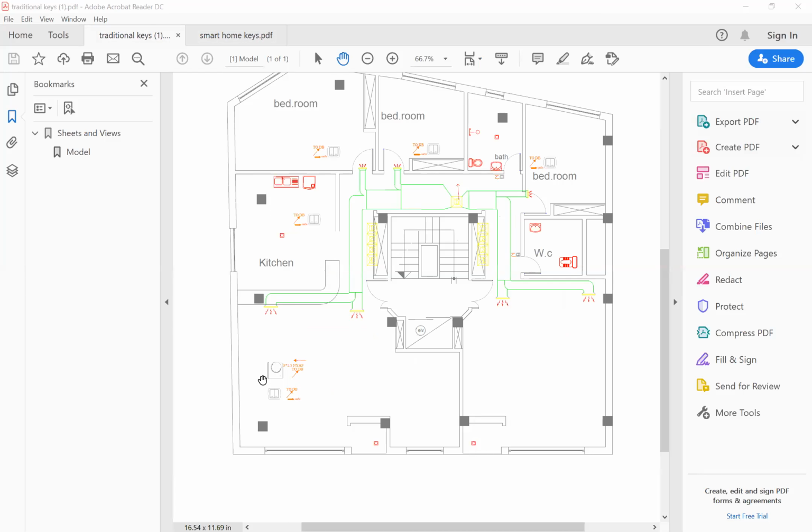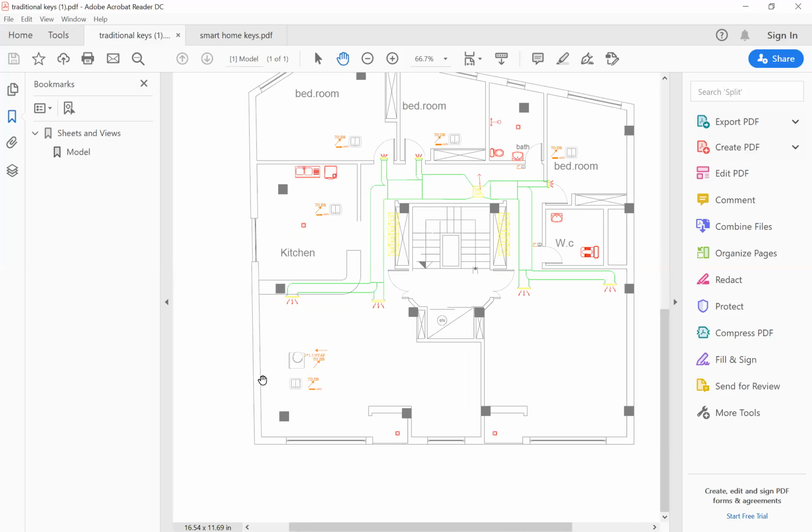So if you put, for example, 20 degrees here, the AC works until this area goes to 20 degrees. And maybe this place wants to change to 20 degrees, this room gets freezing because this room is smaller than the living room. And here we don't have any energy saving.